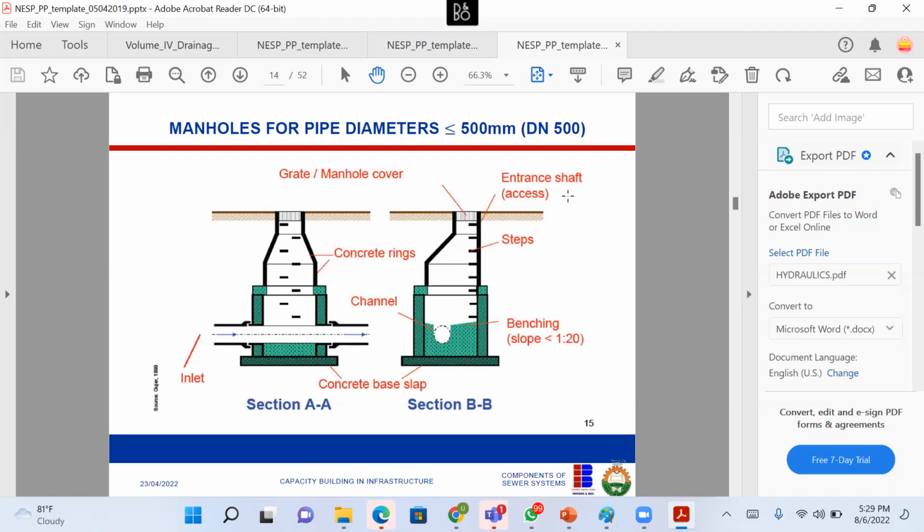It's in the highway design manual. It depends on whether it is over the road or in a bush path. There are other factors. What I'm asking is within a compound. So when you have a home environment within the compound, 600, even 800, is adequate because there's not too much overburden, like car parking and heavy load. Okay, so 600 from the surface. Yeah. All right. Thank you.